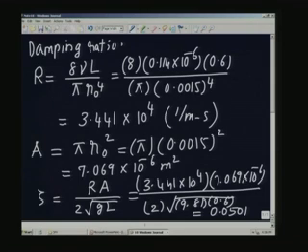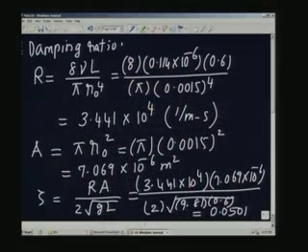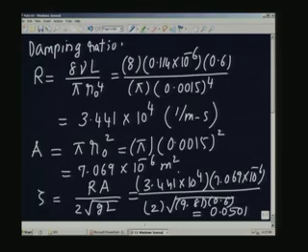What does it mean? It means that it is underdamped because it is less than 1, therefore, we have an underdamped system. If you observe mercury in a U tube manometer, you will invariably see that it is an underdamped system, and if you subject it to a sudden application of pressure on one side, it will go through a lot of oscillations that you will be able to see if you do a simple experiment with a U tube in your laboratory. And in fact, that is the answer B which was required in our problem.